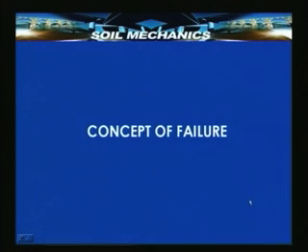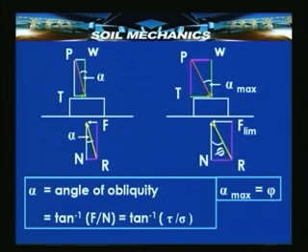Now, having had an exposure to the method of determining the stresses on any plane, let us see what is this concept of failure, which will help us to assess whether under given circumstances of shear stress and shear strength, failure can take place along a plane in a soil. So, what is this concept of failure? Let us go back to physics and try to understand failure along a plane of contact between two bodies which are experiencing friction at the plane of contact.